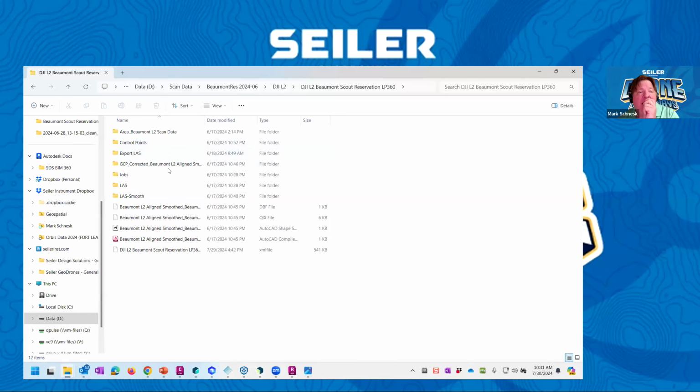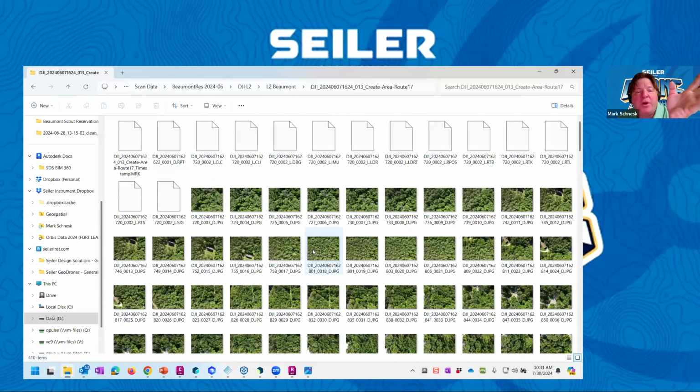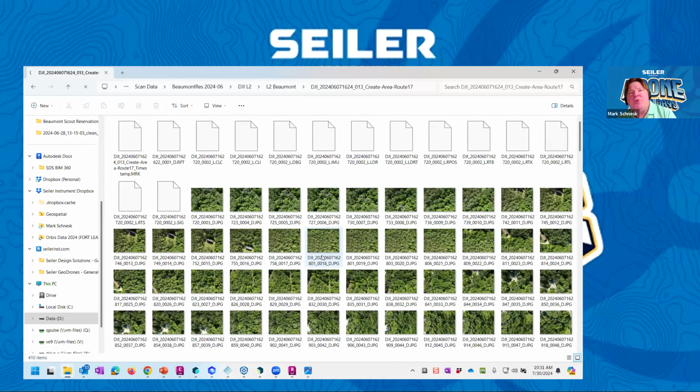You're going to get some photos. Oops, there it is. The photos for the LiDAR for the L2 are strictly there for colorizing the point cloud. Both the L2 and the TrueView series, so the GeoCue TrueView 660, 535, 540, as it's collecting LiDAR data, is also collecting photogrammetry that's going to be used in the software to colorize the point cloud. Other LiDARs, like the Wingtra LiDAR, do not have a camera on board, so the LiDAR is going to be colorless.